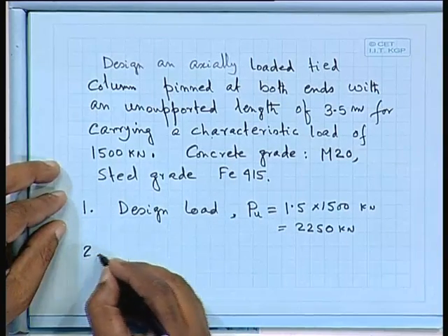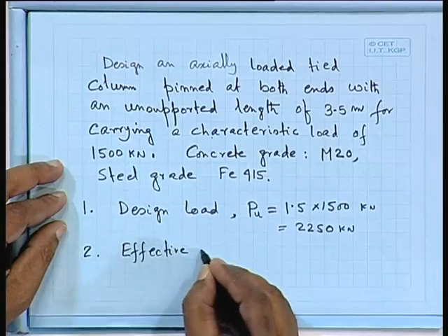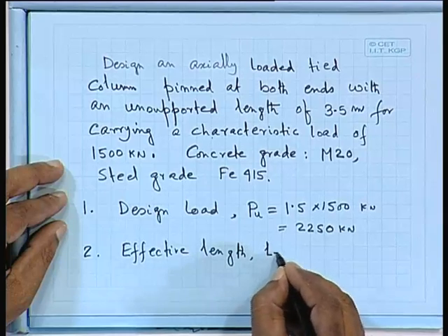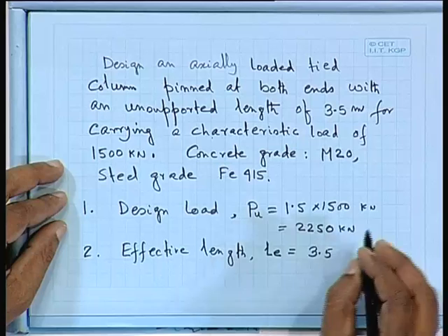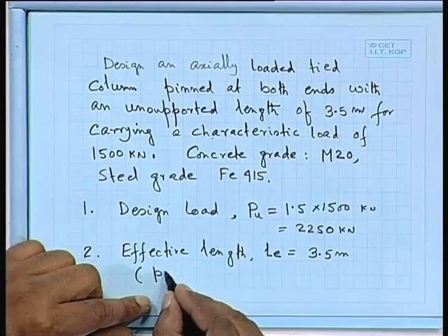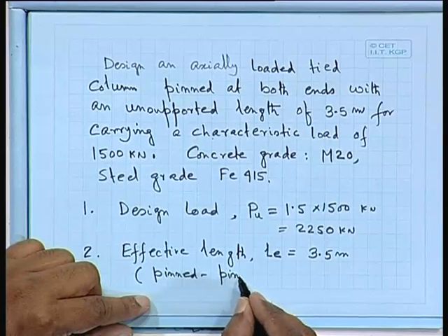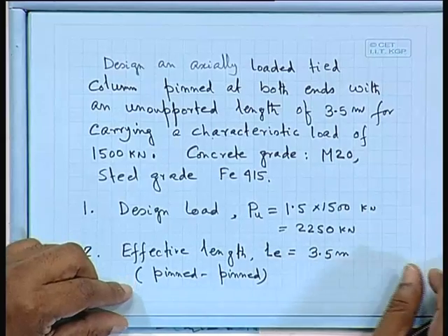What about the effective length? LE will be the same as the unsupported length, because it is pinned condition.